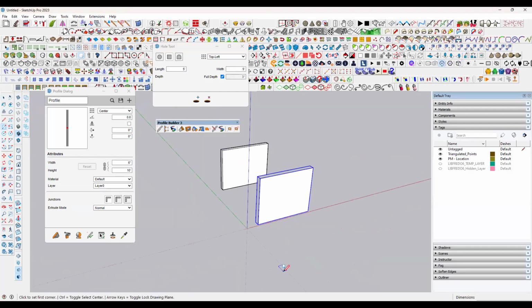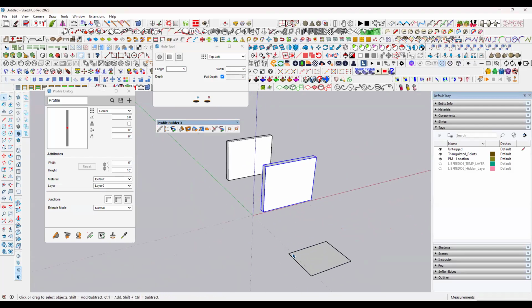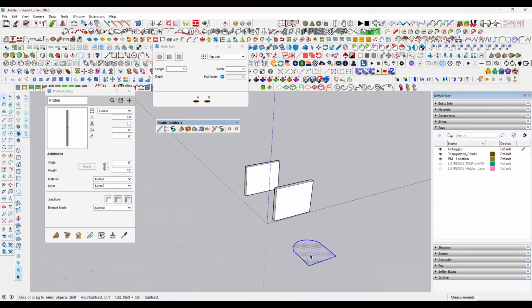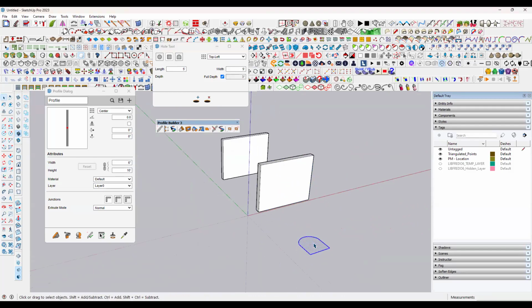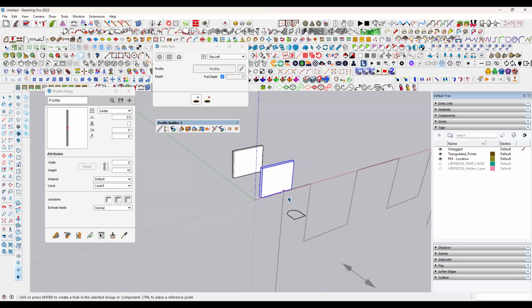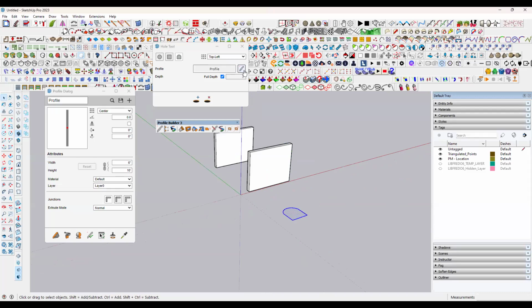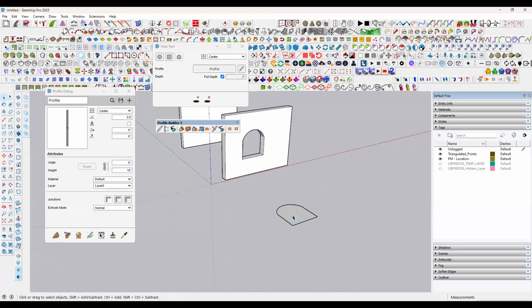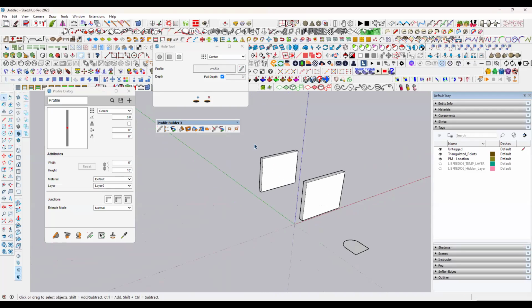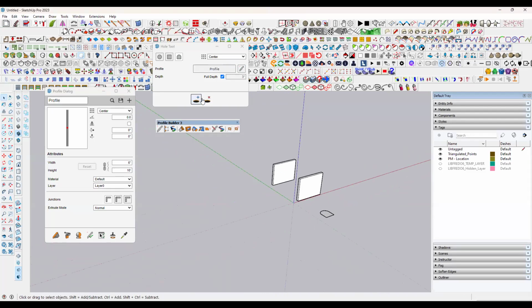But not only this shape, you can take any shape here. I'm taking maybe one arc, from here to here. I can just scale this one directly maybe here. Now I can use it. This is my profile, and now click here. See the same profile, I can apply. Select this one. Create a profile, maybe like this. Click OK. Now click this one. The same thing. See, the same profile, I can easily cut that. Like that. However many walls are on this side, every wall is going to be cut.